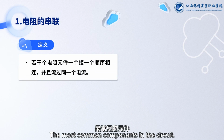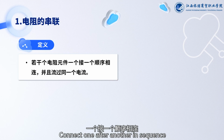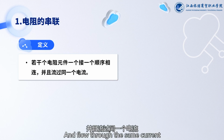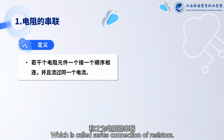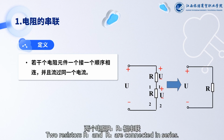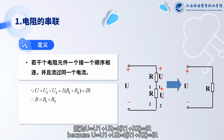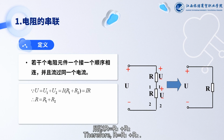Resistance is the most common component in the circuit. Several resistance elements connected one after another in sequence, flowing through the same current, is called series connection of resistors. As shown in the figure, two resistors R1 and R2 are connected in series. Externally, they can be equivalent to a resistor R, because U equals U1 plus U2 equals I(R1 plus R2) equals IR. Therefore, R equals R1 plus R2.